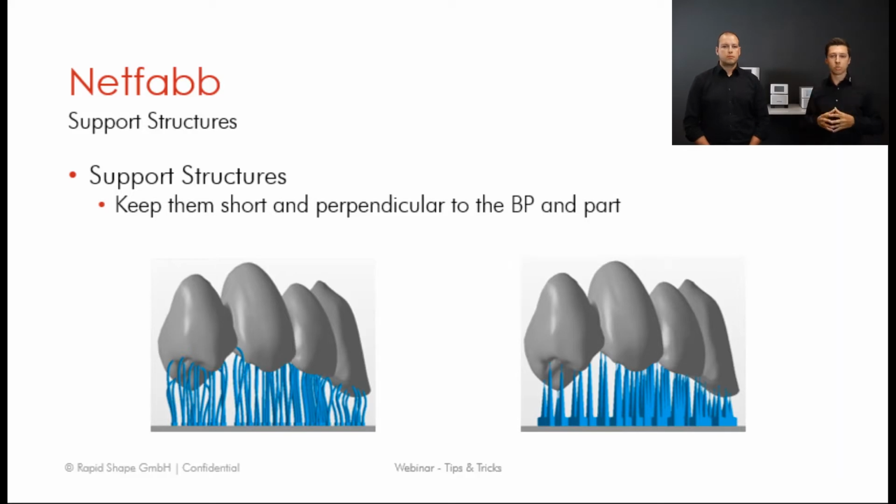So our recommendation, or our tip, is, if you're doing something like this, or you're not experienced in using supports, keep them straight, so perpendicular on the platform and on the part. And of course, don't make them too long. If you're making them too long, they're also getting unstable or fragile, and they will most likely fail. So this is a really important thing if you're playing around with the supports.